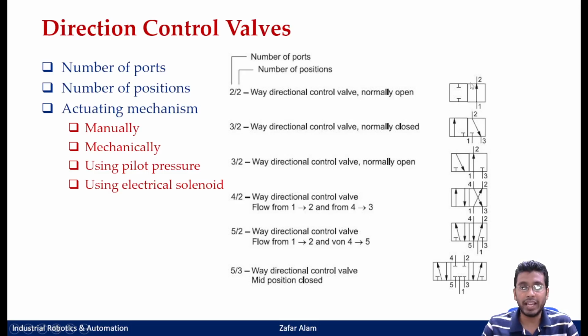In actual valves they would not be like this, they will have two ports, but these ports will not be divided into square blocks like this. These square blocks are only for our understanding and for better drawing of your hydraulic or pneumatic circuits when you actually form a circuit on your own. In your actual valve it is only the spool that shifts.